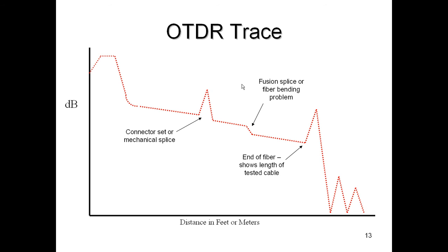And certainly if you have an OTDR handy, the smart thing to do after you have hooked up a fiber link and it's working is to shoot it with the OTDR and retain that image, store it electronically or store a printed copy of it. That way, if there's a problem later, you can hook the OTDR up again and shoot the fiber again and see if maybe the fiber has been cut or damaged in the process, that it has changed from when it was good and now it's not working properly. We can do that if we store our OTDR traces either electronically or as printed copies.